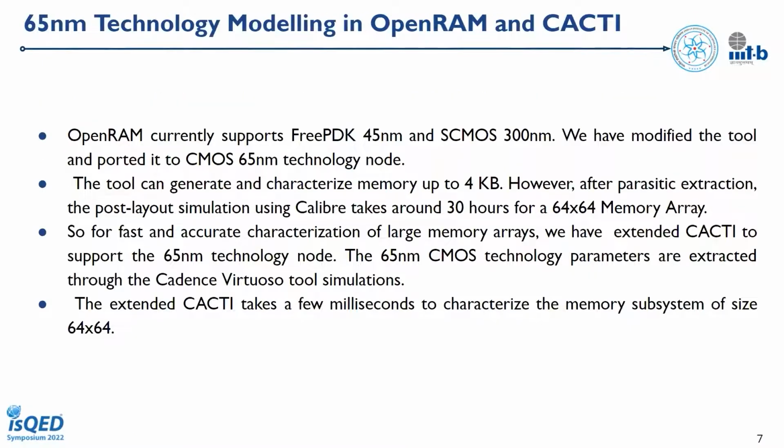65 nanometer technology modeling in OpenRAM and CACTI. OpenRAM currently supports FreePDK 45 nanometer and SCMOS 300 nanometer technology nodes. We have modified OpenRAM and ported it to the 65 nanometer technology node. The tool can generate and characterize memories up to 4 KB.